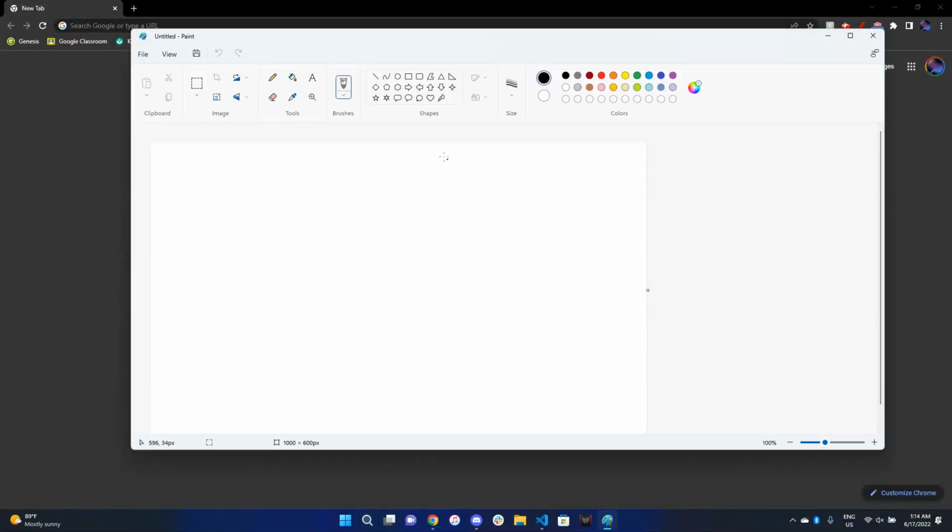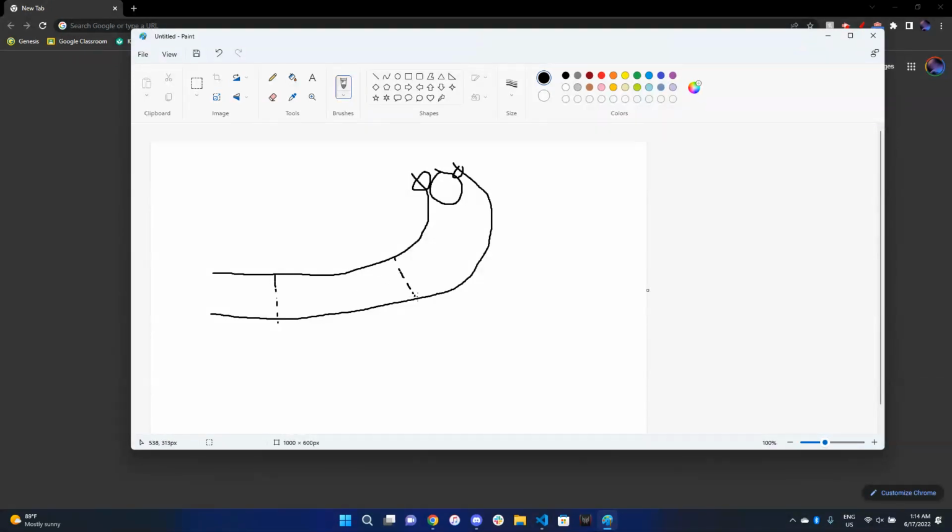So you can imagine on a robot, right? Let's say this is the conveyor for our shooter, and the shooter's up here. You've got your flywheel, your other wheel, and let's say that's a ball. What beam breaks allow us to do is keep track of how many balls are within our robot at once. If you have a beam break somewhere near the shooter, like right there, then if we cross this first beam break, that means there's a ball somewhere in here. And once we cross the second beam break, we know the ball's already been shot.